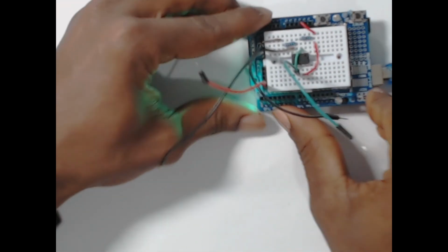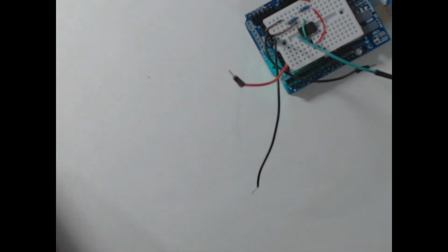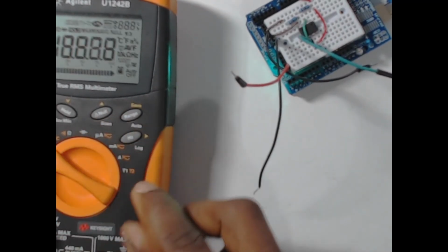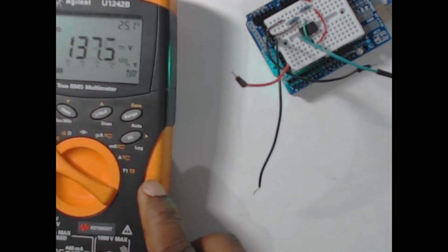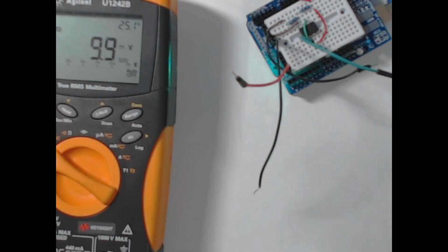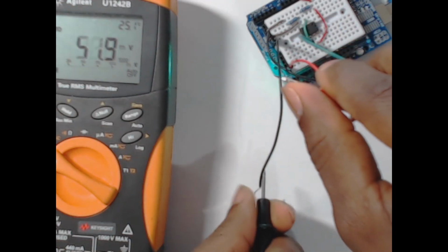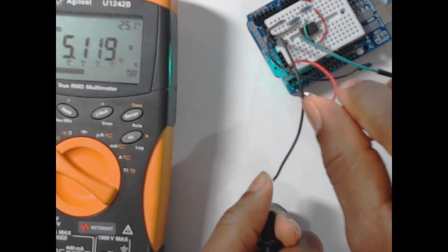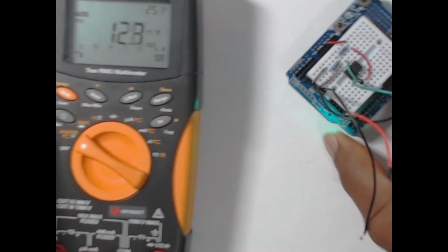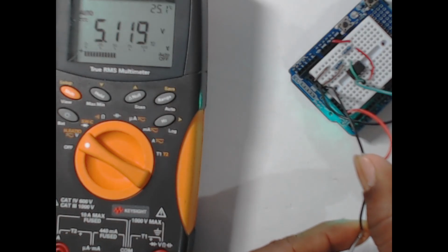and what I'll do now is connect my multimeter and put it to DC. So we know that this is positive here and negative here will give us 5 volts, and it says here at the bottom you got your 5 volts across there.